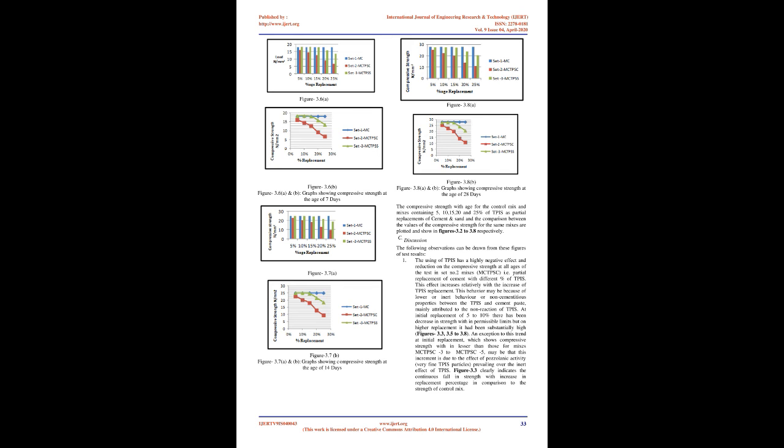For example, compared with compressive strength of control mix, average percentage compressive strength for mixes MCTPSS1, MCTPSS2 and MCTPSS3 are 99.79, 98.80 and 96.9%, i.e. very negligible fall in strength, i.e. -0.22, -1.20 and -3.10% respectively. This behavior refers to the pozzolanic activity as well as filler attribute of TPIS with very fine sand particles, as previously mentioned in the literature section. Figure 6.4 clearly indicates the overlapping of graph lines of compressive strength with increase in replacement percentage up to 15% in comparison to the strength of control mix graph lines.